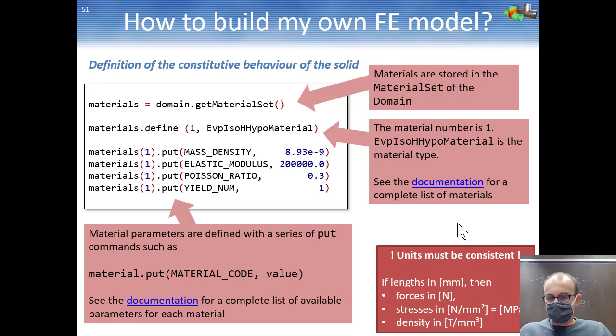So here also a remark about the units. I don't know if you have used a lot of simulation codes in the past. So there are no units in Metafor. So it means that you can choose any unit, but everything should be consistent. So for example, if all the lengths in your input file are written using millimeters,